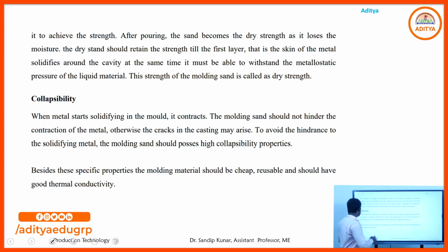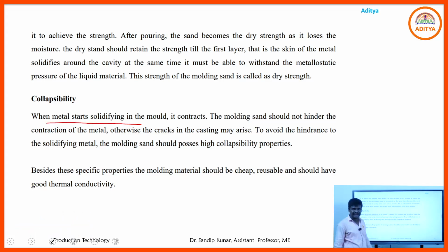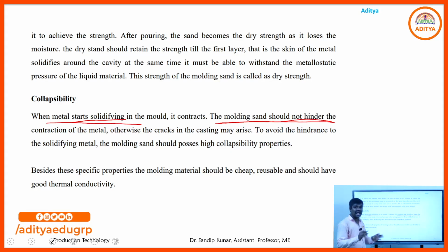Collapsibility means when molten metal starts solidification, it contracts. When metal starts solidifying, it contracts, so some extra allowances will be created. And also the molding sand should not hinder the contraction of the metal. That is very important. Otherwise, if it hinders, the produced part will crack, means cracks in the casting may arise.